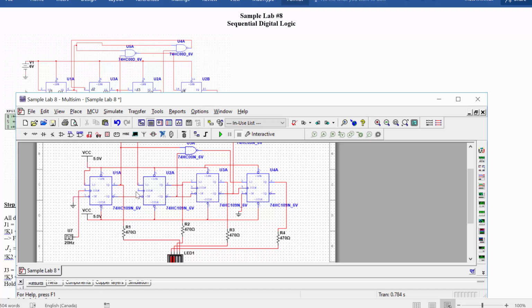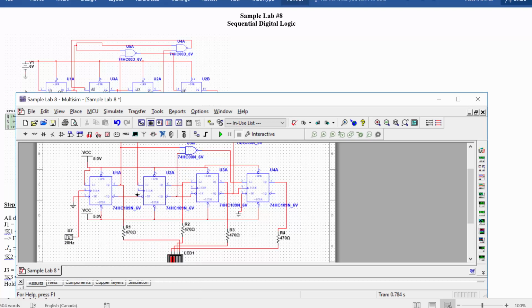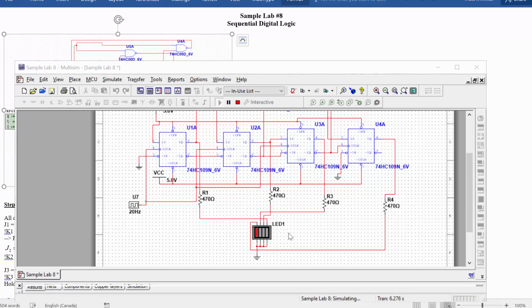So there is the first clock. The first 3 of these are all clocked off of the input. Rather, they're all coming from the digital clock. And that's connected to that. Got to be careful here to hook it up to the right thing. But the last one is clocked differently. Okay, so we've got our counting working. And yes, that does reproduce what we were seeing from the timing diagram and what we predicted.